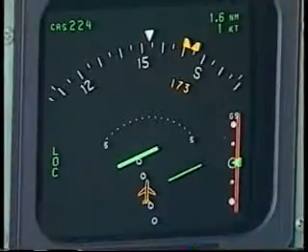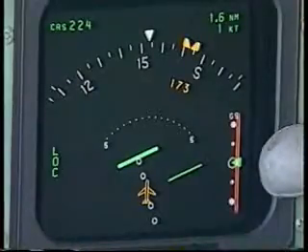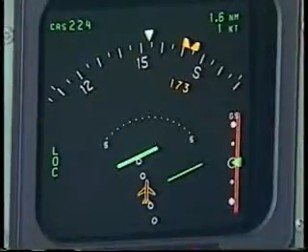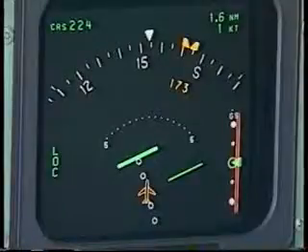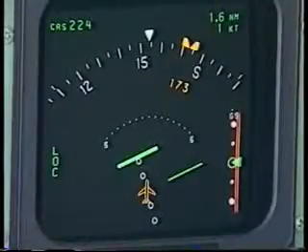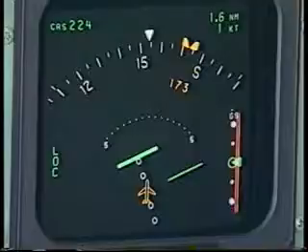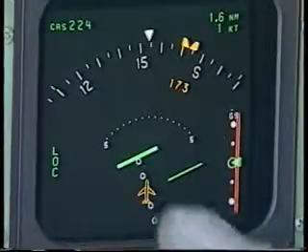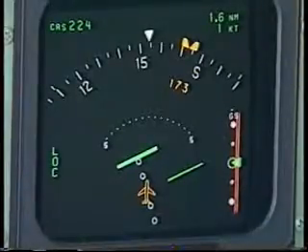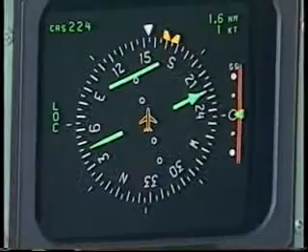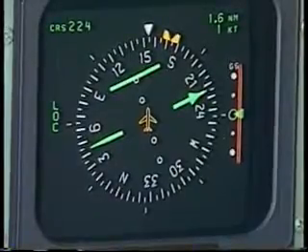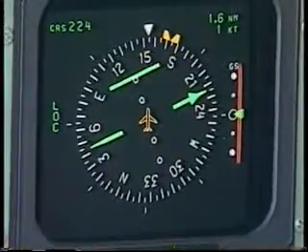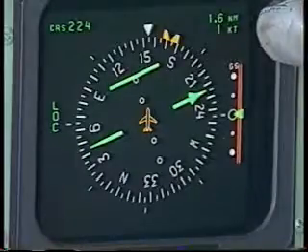Now, notice that there is a glide slope scale and pointer on the right-hand side. This only appears with the localizer selected when the dial course is within 105 degrees of the aircraft heading. Notice also that it has appeared on the EADI. The other point to notice with the localizer is that the single arrow bearing pointer is gone. Press Nav Map again to switch back to the HSI format, and the presentation changes to the full compass rose. Distance will also be blank unless the ILS has co-located DME.